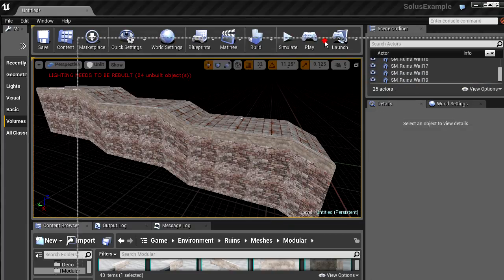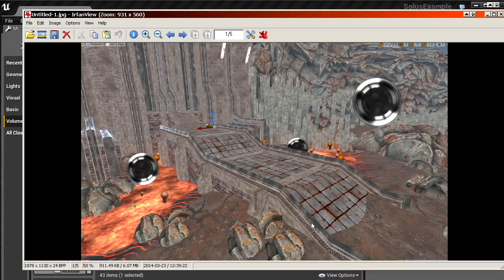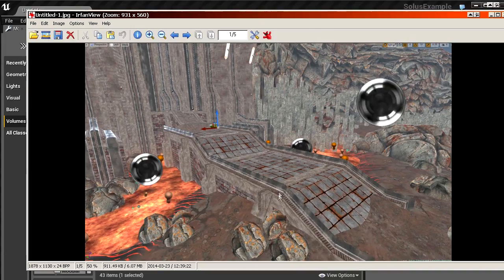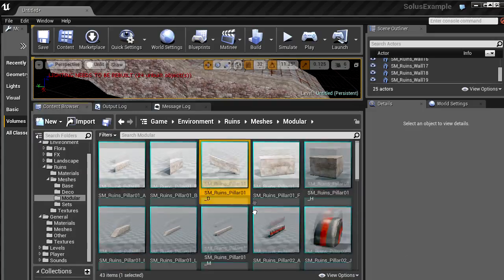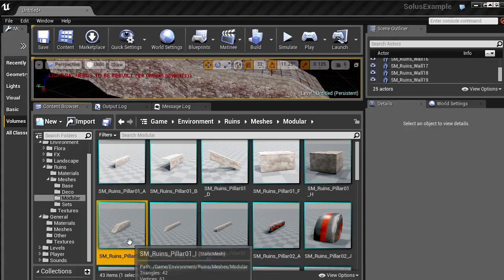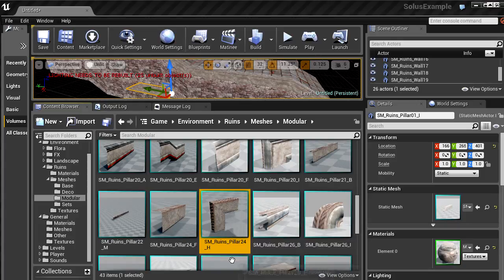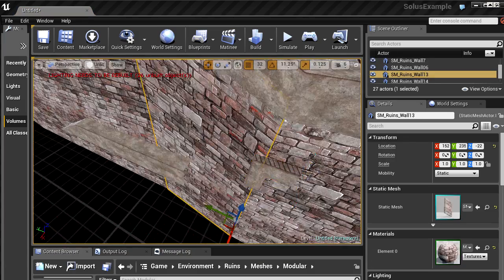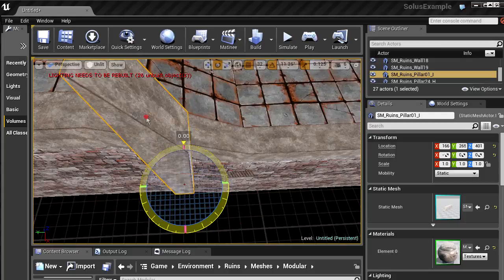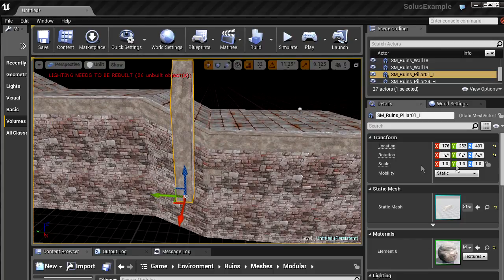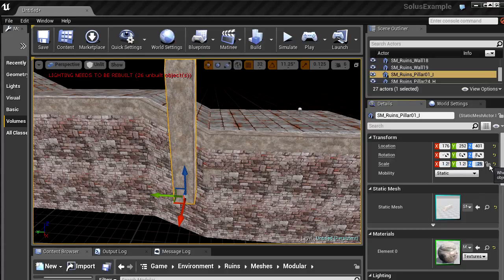That's that. Then there is this metal thing running over the top as well. And there are some pillars on the side. So let's do those pillars first. Pillar is this one. It's pillar 1i. This small corner sticks out at the top, so you might as well just add that as well. It's a 24H. Rotate this one. I think I probably scaled it a little bit, so I'm going to scale it to 1.25. Also, you can press the lock button here, so it automatically scales uniform.